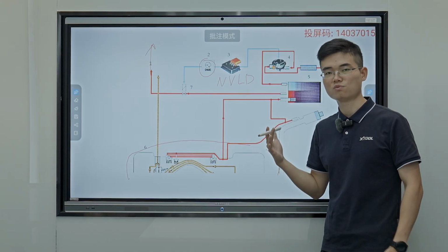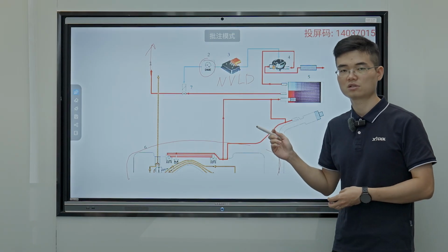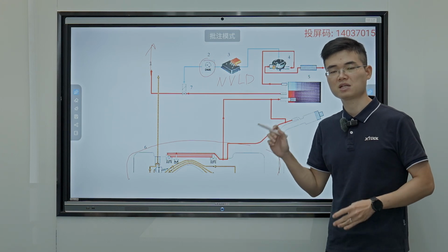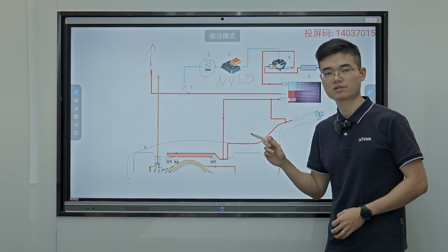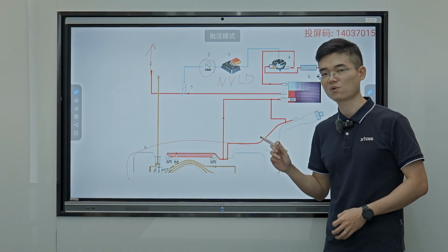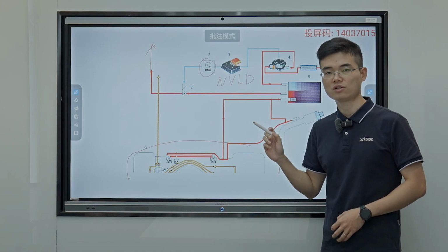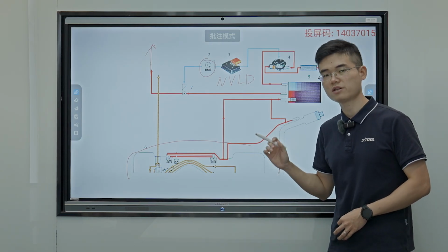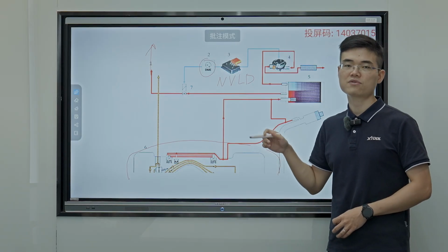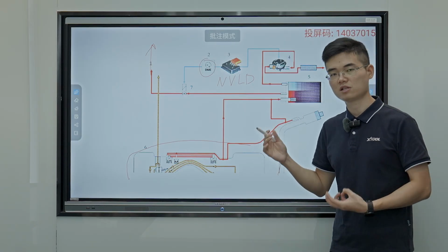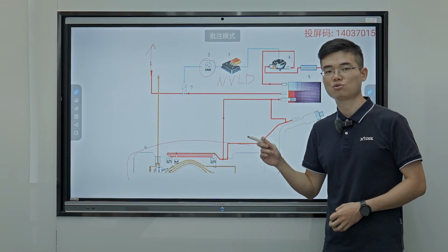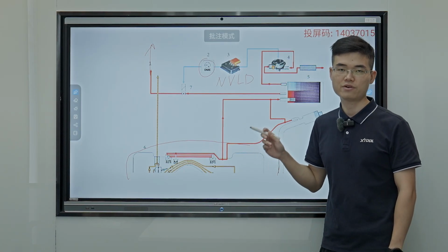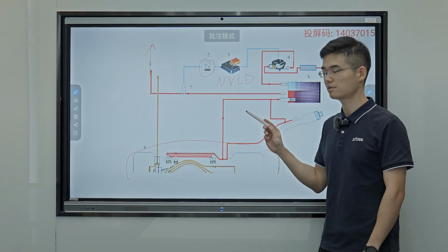Before we perform the fuel tank leakage diagnosis, there are several conditions to be met. The first is to make sure that the engine is cold. We need a cold engine start. If it's not cold, it should be cooled down over 8 degrees Celsius and last for at least 1 hour. The second condition is that the altitude should be lower than 2,500 meters. Another condition is the battery voltage should be between 11 to 16 volts. And the environment temperature should be higher than 4.5 degrees Celsius.